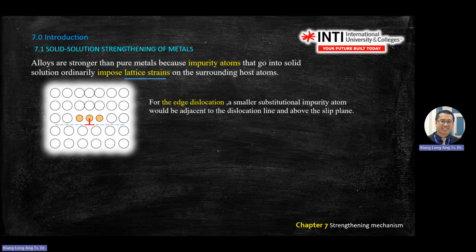Now previously we learned about the defect edge dislocation, which is the inverted T. Inverted T means at this section here, there is a hole. There's a discontinuity of the host molecule or sphere, so there's a space there. You need to fill in the hole. You can fill in by two ways, either substitutional impurity or interstitial impurity.